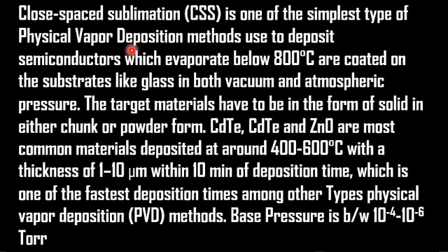in a physical vapor deposition reaction chamber without any type of chemical reaction, and is transported onto the surface of the substrate, and then onto the surface of the substrate the evaporated precursor material is deposited, condensed and converted into a thin film.